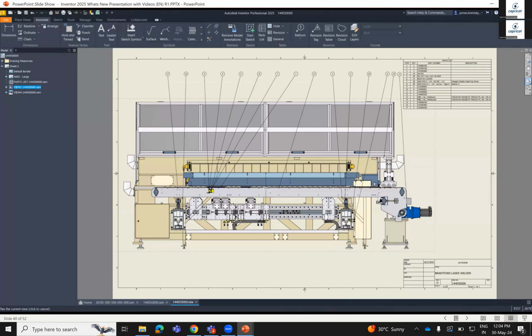See, masking is there, but I know designers will ask whether this particular dimension has been inspected or not. So you cannot use this option for inspection purposes in the documentation. If you have hundreds of dimensions in one document and you are checking every particular dimension to see whether it has been inspected, we cannot use this for that purpose. Now, if some background lines are disturbing, and I want to highlight only that particular text, I can do that with the background mask. Okay.